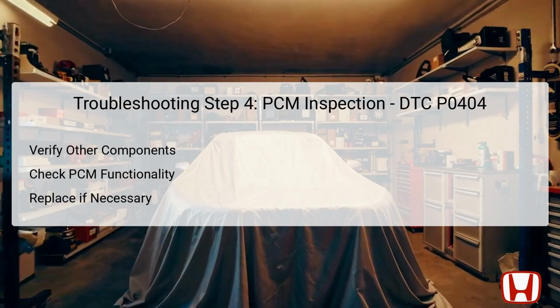In the fourth step, if previous inspections yield normal results, the focus shifts to the PCM itself. Confirm that all other components related to the EGR system have been functioning correctly to eliminate other potential causes. If it is determined that everything else appears normal, further testing of the PCM's functionality must be executed.